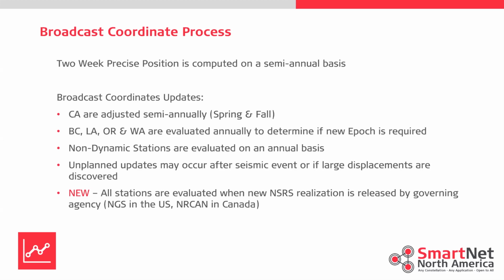We've only had to do Oregon and Washington once every 2 to 3 years, but we'll take this opportunity. I think the last time we did it was 2018. So we will take the opportunity to update to 2020 here as well. All non-dynamic stations, meaning all stations in SmartNet, are evaluated. Well, they're really evaluated on a daily basis, but with a really hardcore evaluation on an annual basis to make sure that there's nothing really out of sorts. And then unplanned updates happen after seismic events or when large displacements are discovered.